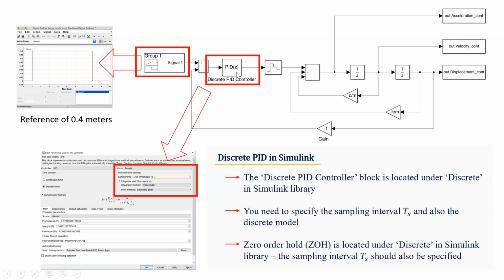Okay, MATLAB and Simulink, well, Simulink allows you to effectively, I would say, get away with committing murder. So we're mixing time domains here. This is in the continuous time domain. This here is in the discrete time domain. But effectively what this is going to do is capture, because in practice your system is in fact continuous, but because we've got a discrete controller here, it's only going to capture the information at every sample point.